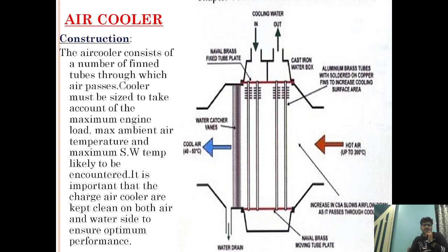So as the air passes through the fins, it will reduce its velocity to say 2 meters per second. As the speed is reduced, the contact time will increase, and hence the efficiency of heat drawn out from the system and the air cooled will increase.